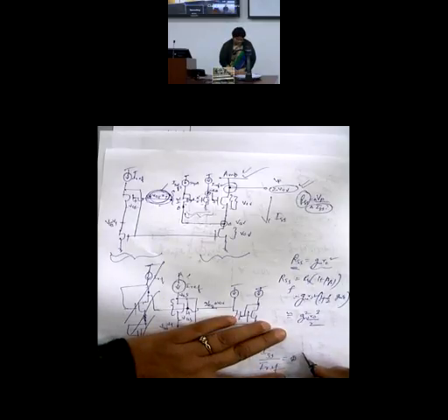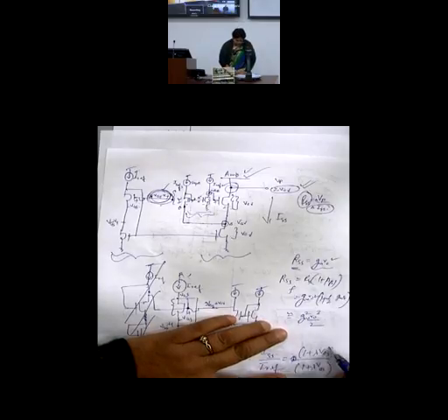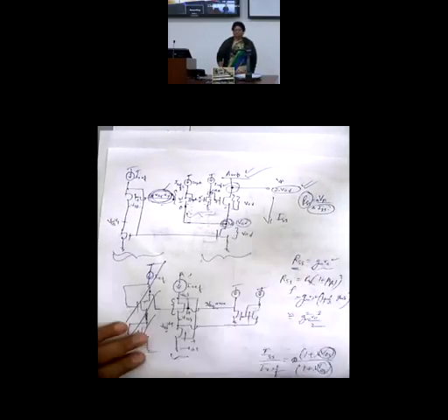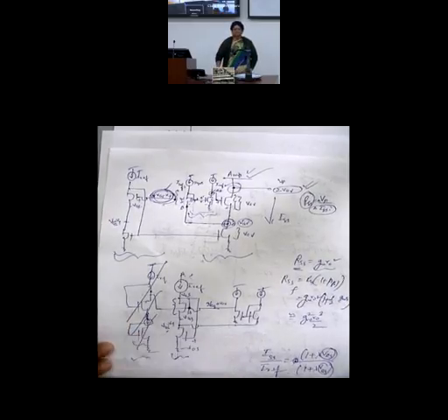Now, remember, it would be dependent on the 1 plus lambda VDS parameter. If everything else is the same, these parameters can be different because of the VDS difference. What is the VDS here? It is V overdrive. Now look here, if I go for this solution, what is the VDS here? It is VGS, so they will be different.